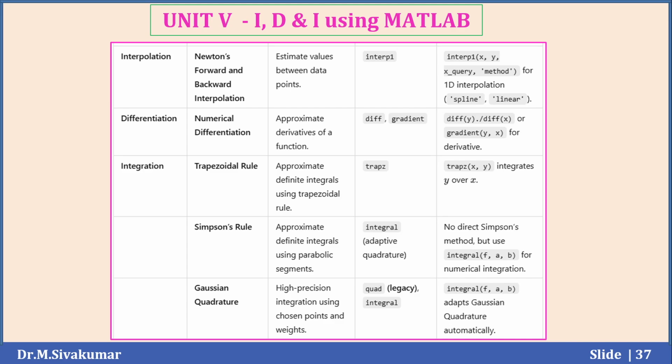Here, the subtopic of interpolation is Newton's forward and backward interpolation. The purpose of this interpolation using MATLAB is to estimate values between data points. What is the inbuilt function? The MATLAB inbuilt function is interp1. What is the usage or syntax for this one? interp1(x, y, xq, method) for 1D interpolation, with methods such as spline and linear.